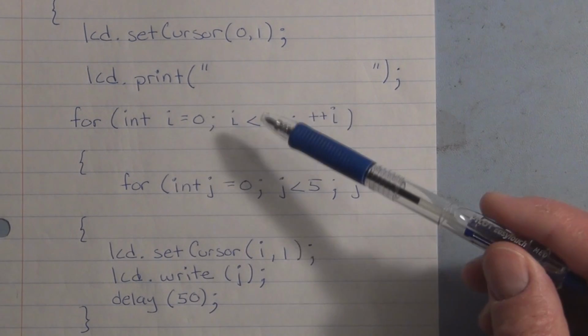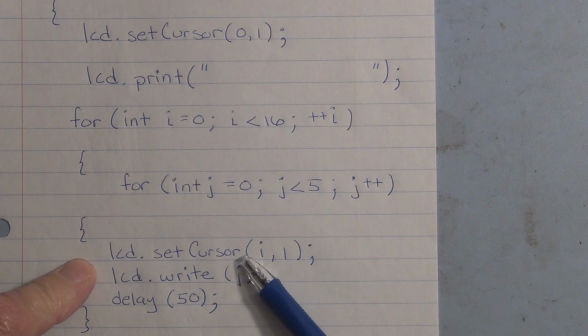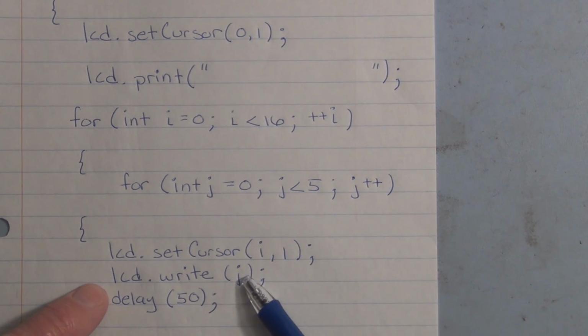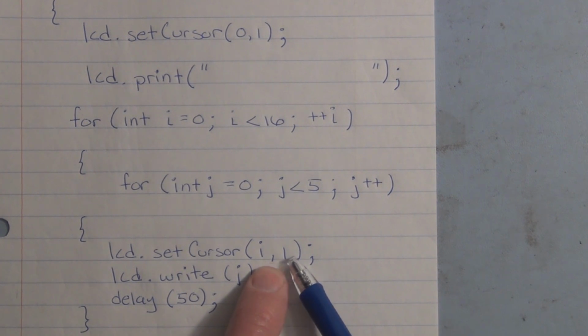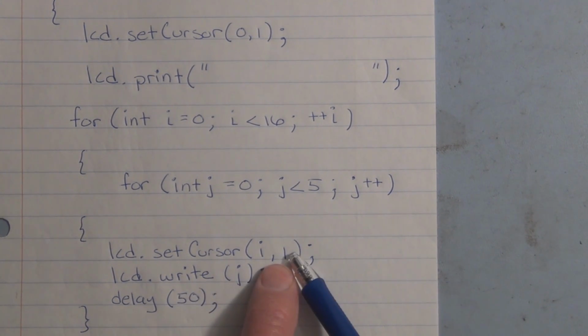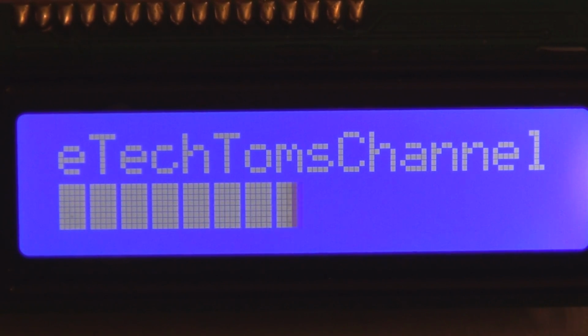And that's all achieved with these 2 for statements here. And then this is the lcd.setCursor. This is changing the cursor position. And this is the lcd.write(j), which is the special characters. So this is setting the cursor position, and this is printing 5 special characters per one of those 16 cursor positions. So that's about it on how a progression bar works.